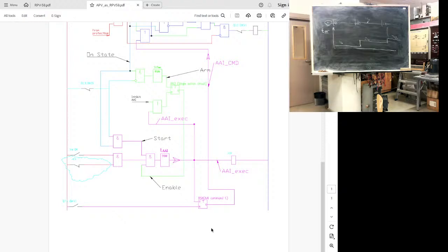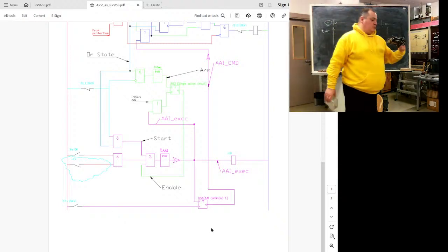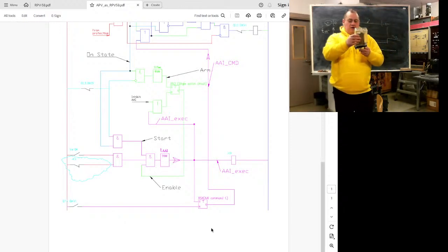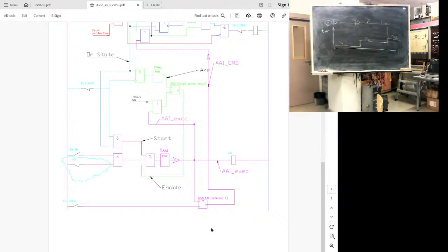Another version, wait, yeah, this was the early version. Later, this kind of thing. No, this one has only one coil and copper barrel. One second. The later version had 2 coils and a barrel. This one with 2 coils, one coil and second coil. The two coil version will hold the command switch on until the switch really switches on.